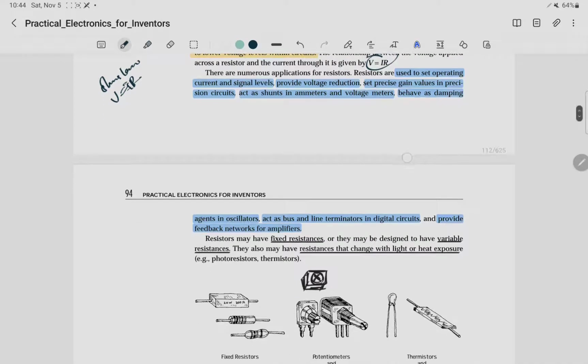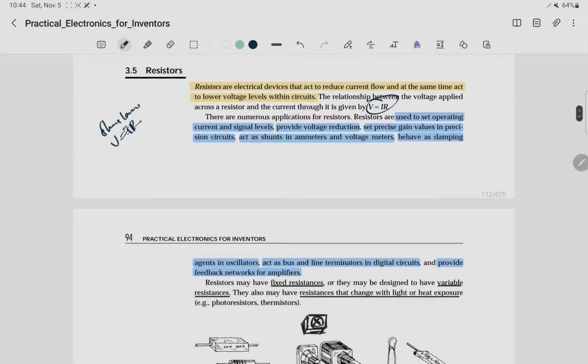which you're seeing here. There are very many applications of resistors. The simplest application that I can give you is when you have your battery and an LED. Let's say you connected an LED here. Then you'd want to put a resistor in order to limit the amount of current flowing through this LED, because if you just connected the LED directly to the voltage, you can easily blow this light emitting diode.